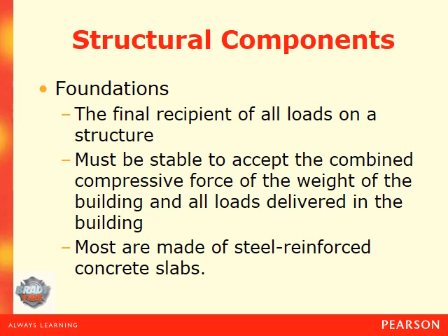So let's look at some structural components now. When we think about our structural loads, everything goes from the top down, and of course gravity is always the eternal enemy of any structure. So the foundation is the final recipient of all loads on a structure. It must be stable to accept the combined comprehensive forces of the weight of the building and all the loads delivered in the building. Most are made of steel reinforced concrete slabs.